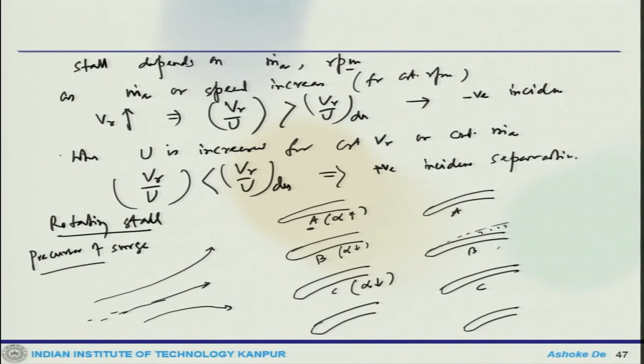Now, at the impeller, the stall rotates in the direction opposite to the rotation of the impeller. So, this causes aerodynamically induced vibration, resulting in fatigue failures in other passages of the gas turbine also. Now, coming back to that characteristics curve.